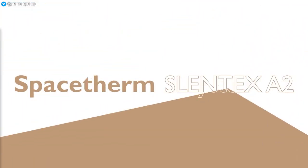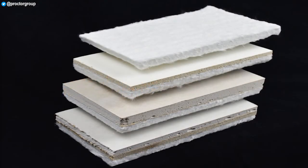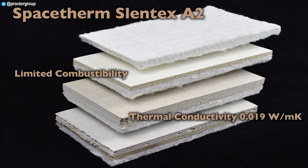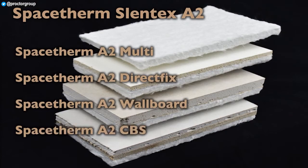SpaceTherm Slentex A2. The SpaceTherm Slentex A2 range of laminates takes the high performance of the aerogel insulation and uses a carrier material with more limited combustibility. This sacrifices a little of the thermal performance, but takes the reaction to fire classification up to A2, giving an ideal mix of physical characteristics for applications which are both space limited and safety critical, such as limiting cold bridging in facade systems. Available in a range of facings, SpaceTherm A2 can also be used to internally upgrade thermally deficient residential high-rise properties without compromising on fire safety.